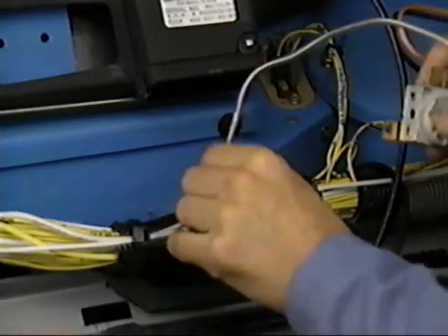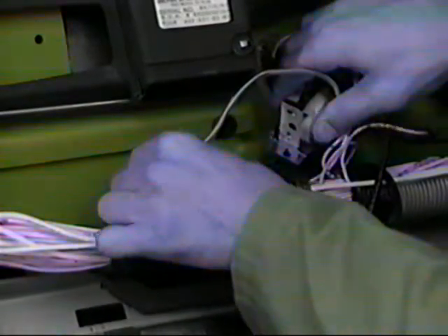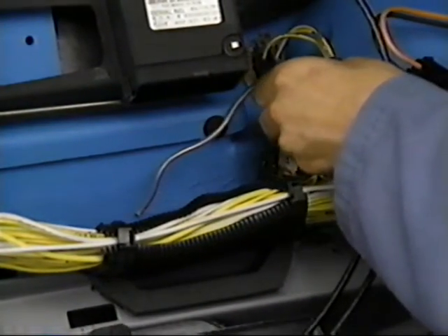When reinstalling the thermostatic switch, the sensor tube must be carefully inserted into the coil fins at least as far as it was before removal. If it's not inserted far enough, the thermostatic switch won't receive accurate temperature readings from the coil. To remove the resistor block, disconnect the harness, remove the screws, and lift the block out.